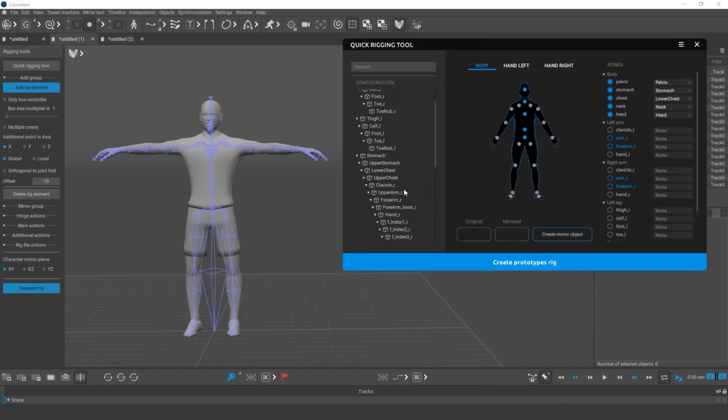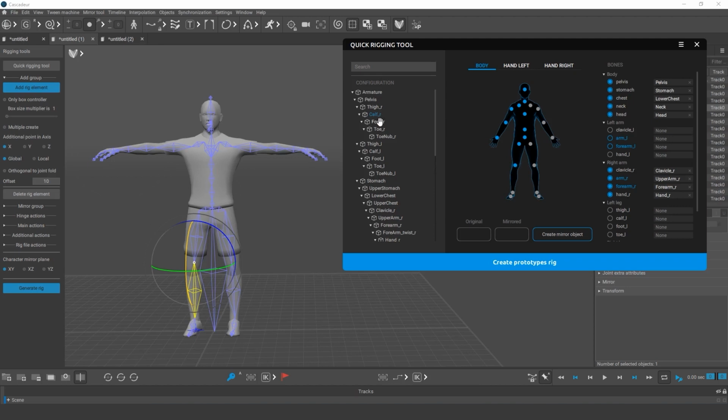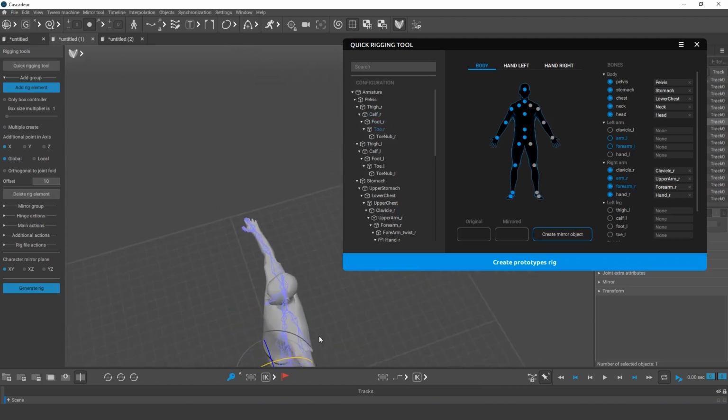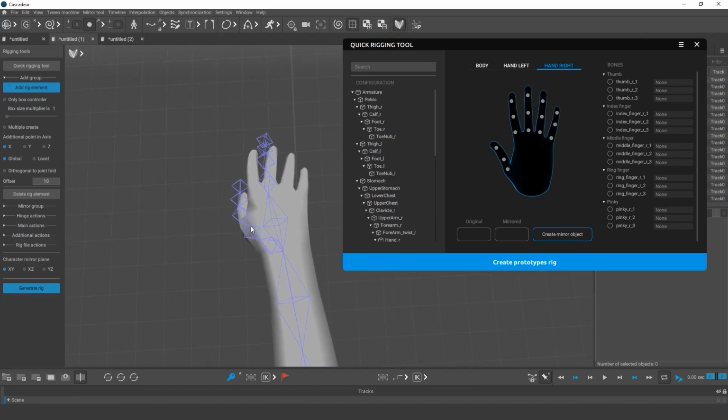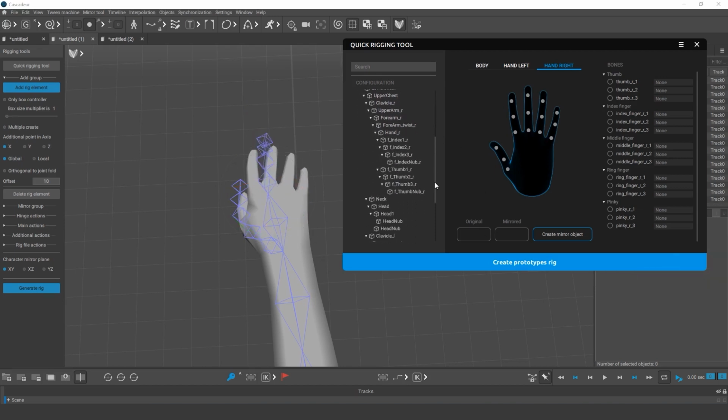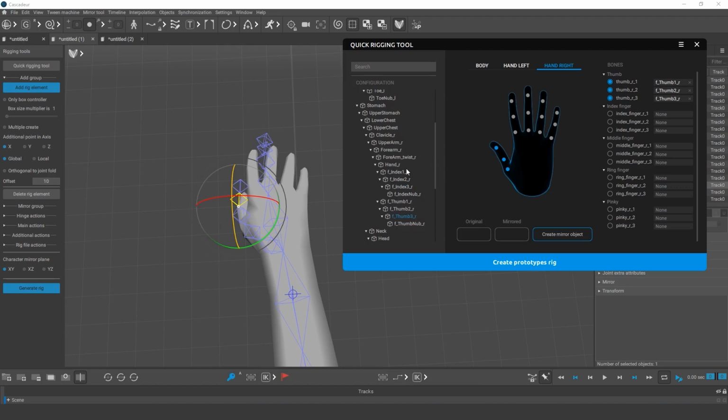For arms and legs, it's sufficient to assign the joints for one of the sides only. Fingers should be set up for the same side. This character only has 2 joint chains for the fingers, one for the thumb and another for the other fingers combined. I'll simply assign the second chain to the middle finger. The fact that some of the finger chains are left unfilled won't affect physics simulations and auto-posing.